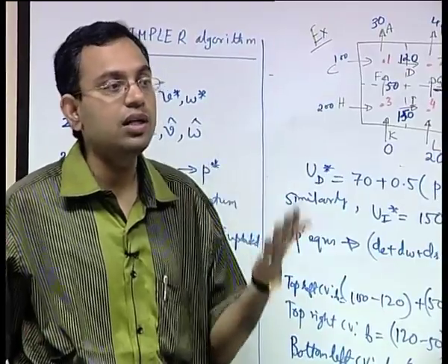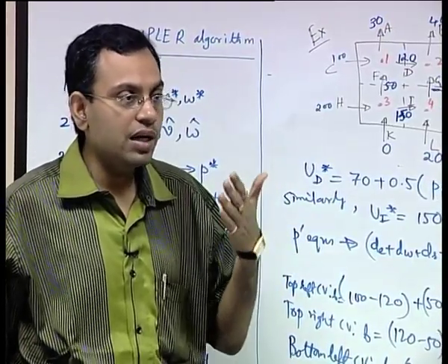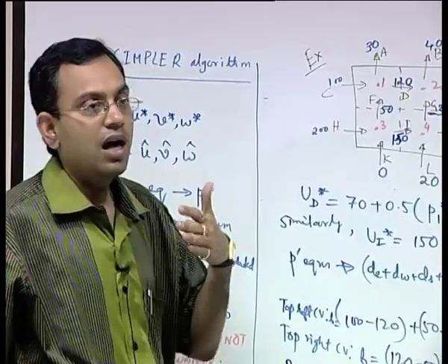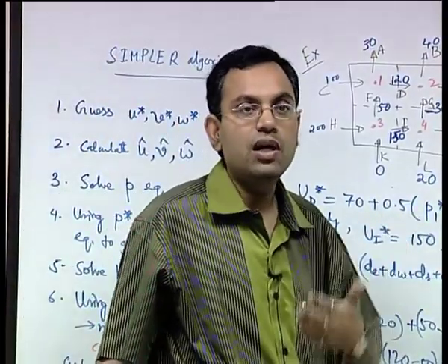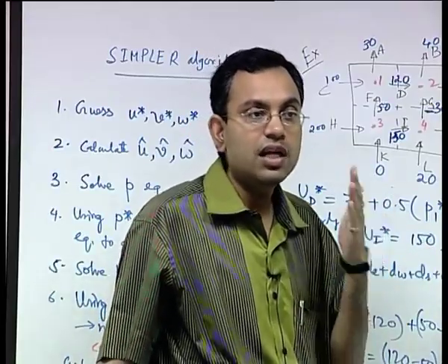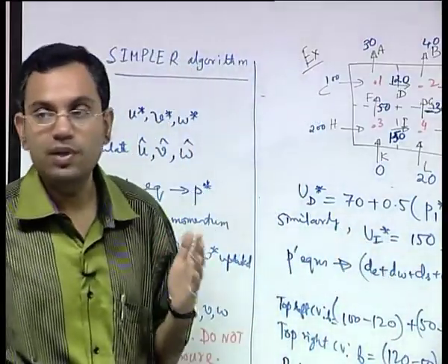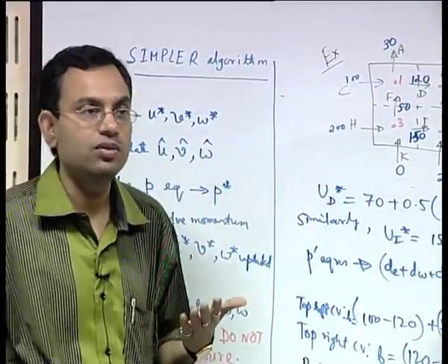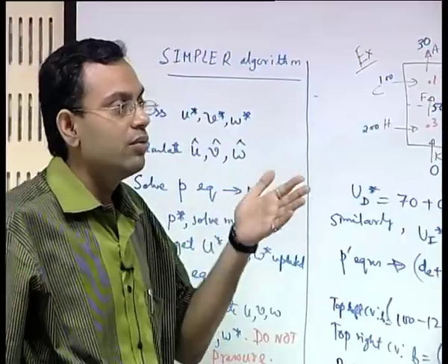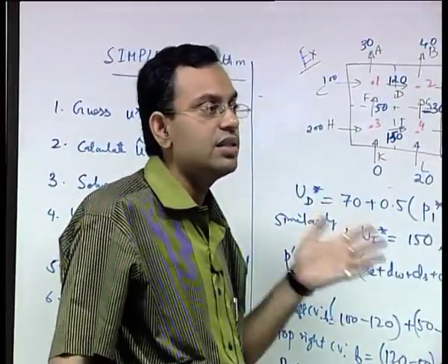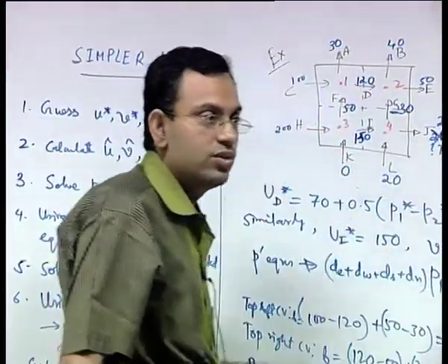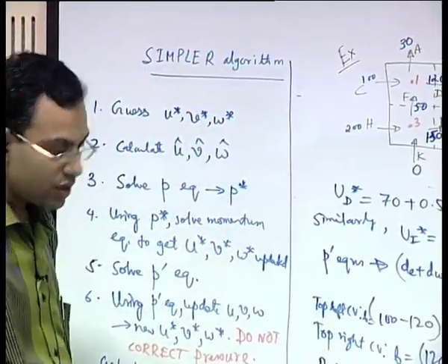So, how to use the continuity equation to address the changes in pressure, or corrections in pressure, or how to correct pressure to come up with a continuity-satisfying velocity field, that particular concept is important more than the description of the algorithm. That concept is brought out from the SIMPLE algorithm, and all other derivatives of the SIMPLE algorithm follow that concept. So, that concept is what needs to be highlighted while we are discussing the solution of the Navier Stokes equation.